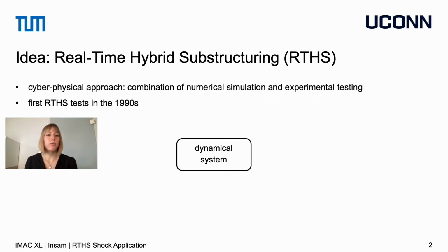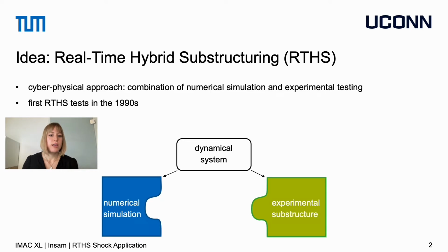Let's start with a quick recap of real-time hybrid substructuring, short RTHS. RTHS is a cyber-physical approach where numerical simulation and experimental testing are combined to analyze the dynamics of the coupled system. Motion and force information is exchanged in real time at a fixed sampling rate.